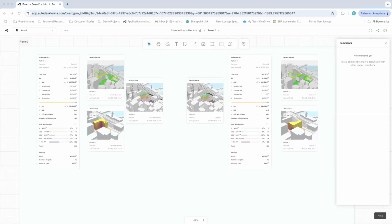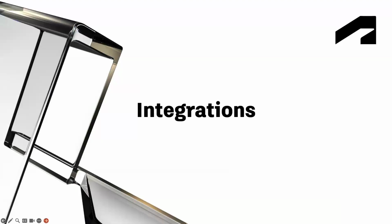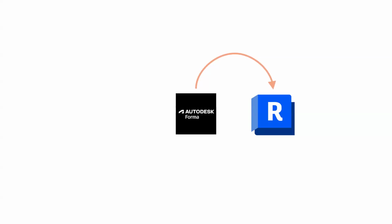All right, so integrations, I said I would talk about it and I briefly did. But of course, we don't expect everyone to draw natively in Forma. I think the most popular extensions that we have are our extension with Revit and our extension with Rhino. With these extensions, we have formalized workflows that we recommend using them for. With Revit, we recommend starting with Forma to create your project, ordering the contextual data, and then either importing a massing or drawing natively in Forma to then send to Revit for further detailed design.